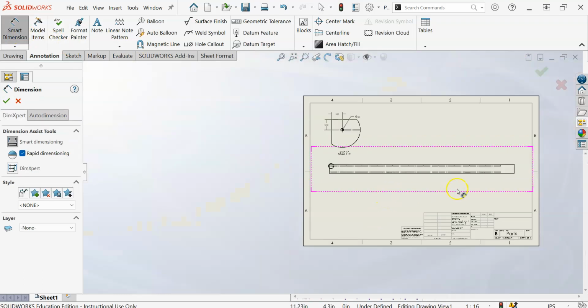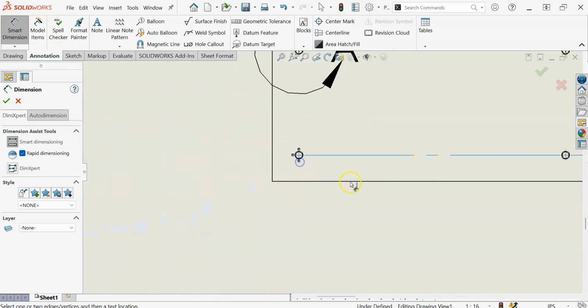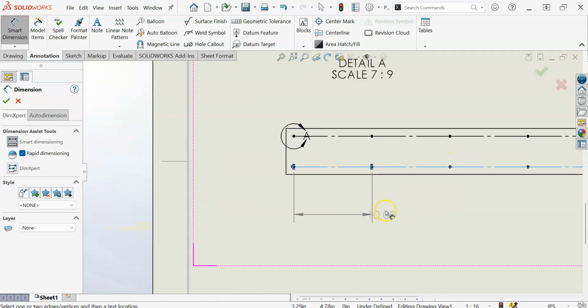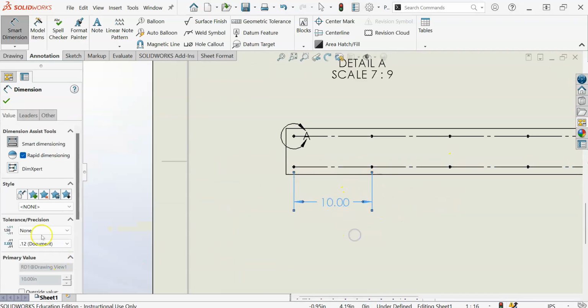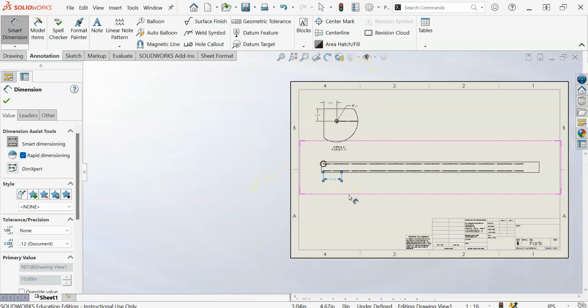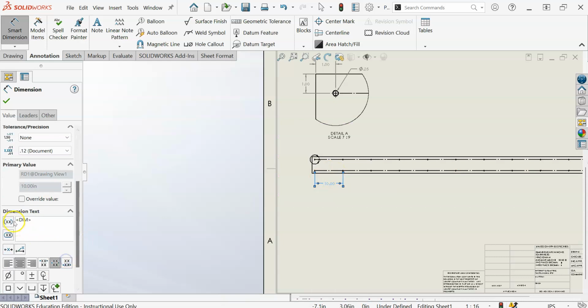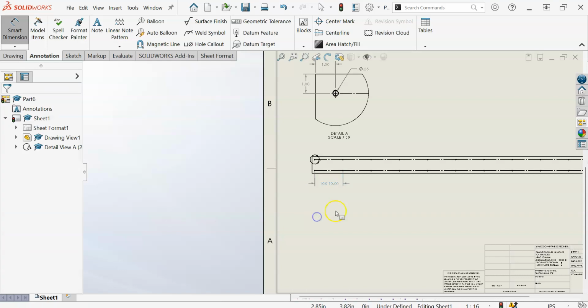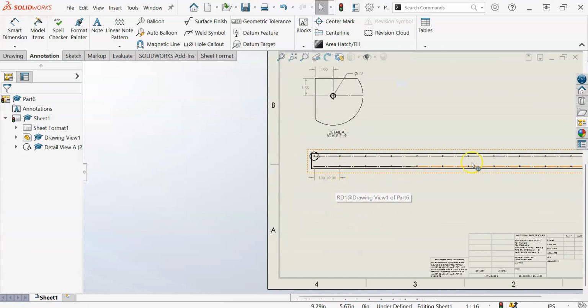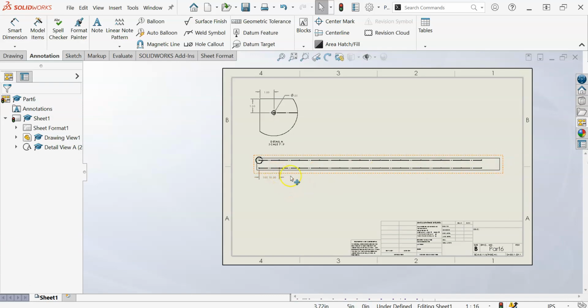in this instance where there's an equal spacing between the holes, you can just add a dimension between the holes. It's going to say 10 inches, and we can count. You can either count the number of times that we use that spacing, so I think it's 10 in our case, and you can just go into the dimension text like we did for when we were talking about hole diameters earlier, and type in 10x, and now they'd understand that there's 10 different intervals.